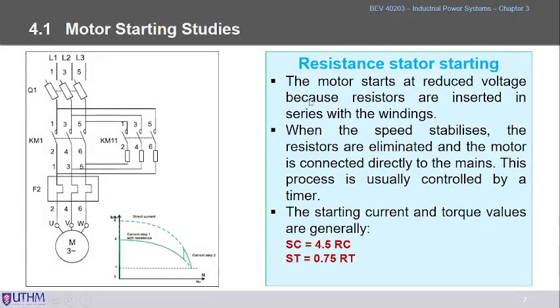And for the stator resistance starting, we put extra or additional resistance just to limit the current, the starting current. By limiting the current, of course we have the voltage drop here, and when we have additional resistance placed in series with the stator during the starting, then we will experience the so-called power losses as well, right?